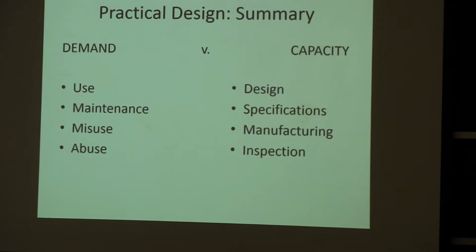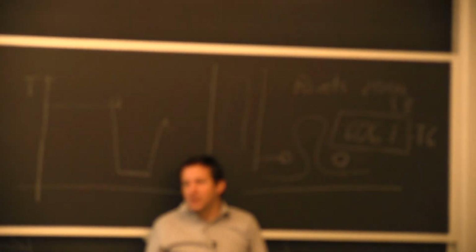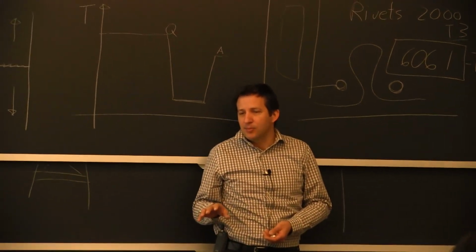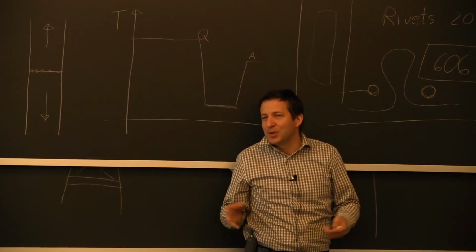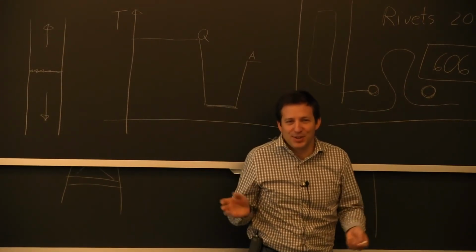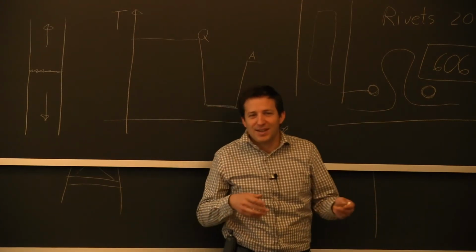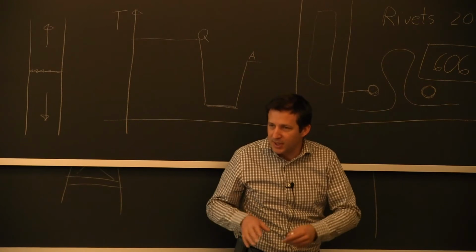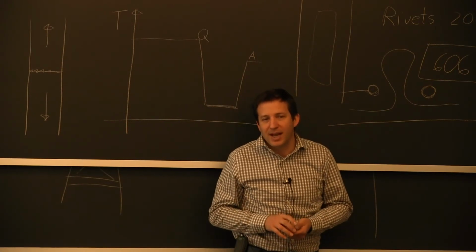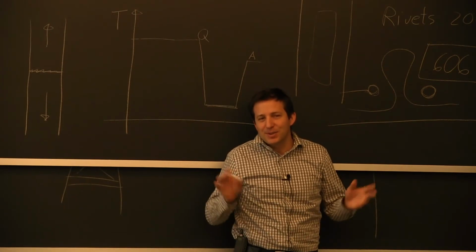On the roof joist example, the guy that qualified so well on a repair procedure was a boiler and pressure vessel welder. So for him, this was nothing. It was the easiest joint. You didn't have to do the preheat and the post-weld heat treatment stuff that you can have to do when you're dealing with very high strength steel. So for him, it was easy.